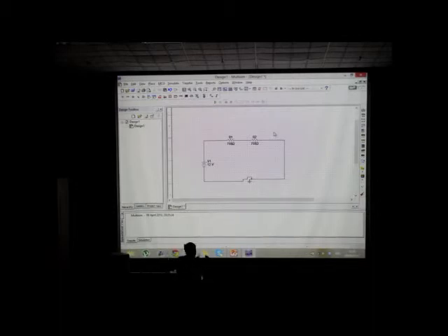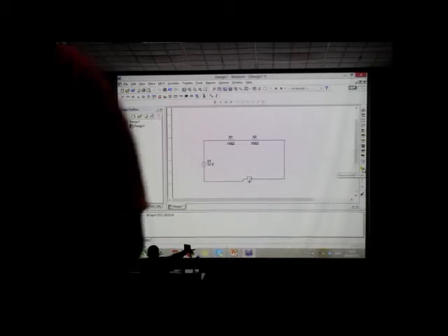But in PSpice, you notice one thing. You click, there's a V and I icon. When you click on that, you can see the current and voltages with the wires, everywhere, how much current is flowing or how much voltage is there. In Multisim, if you want to do something like that, you have to go to your right. There is a yellow icon. It's called the measurement probe. I think you can see it there.